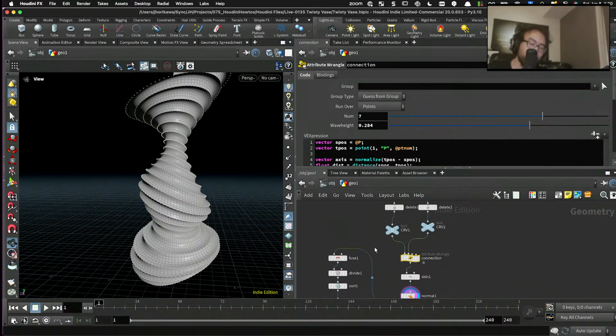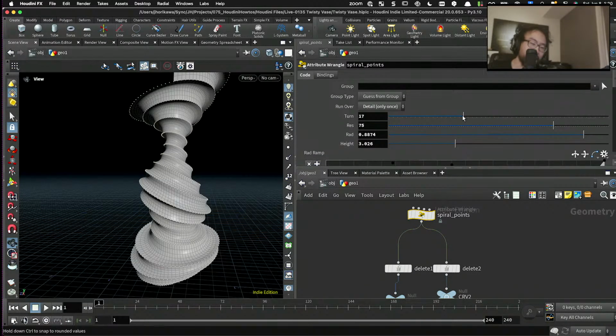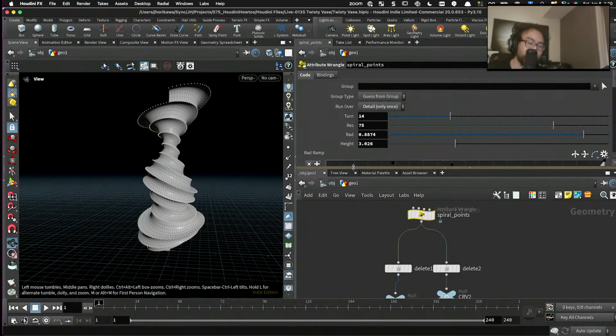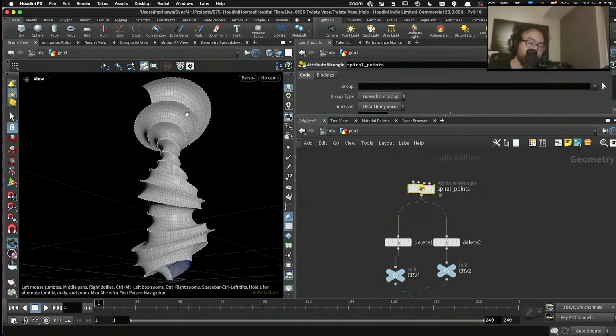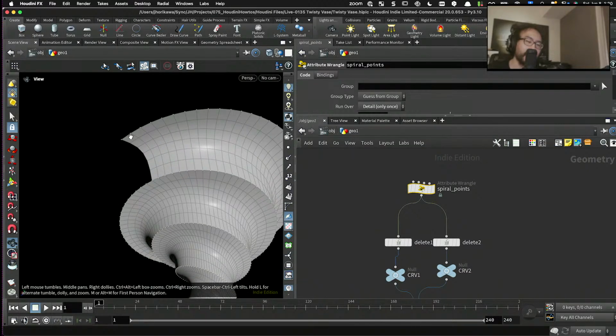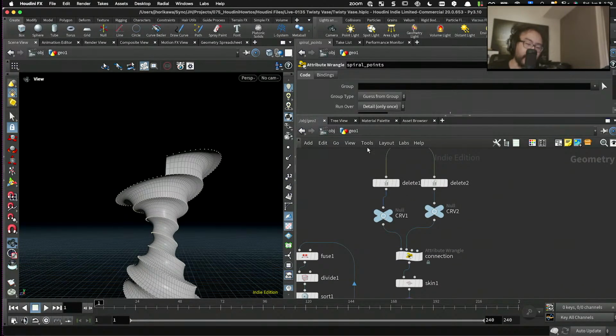Okay, so let's make the shape simple for now so that it'll be easy to see the changes. So first thing first, let's see how we could set the UV. Obviously this is the strip shape, so setting UV will be maybe this cross-section curve will be U and the spiral curve direction will be V. I think that makes sense. So let me do it that way.